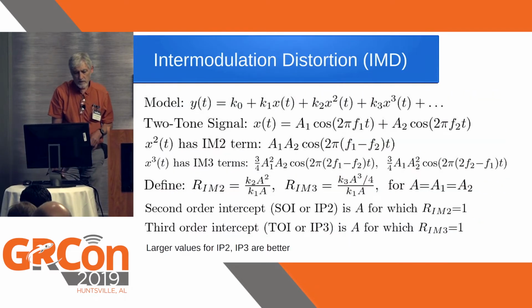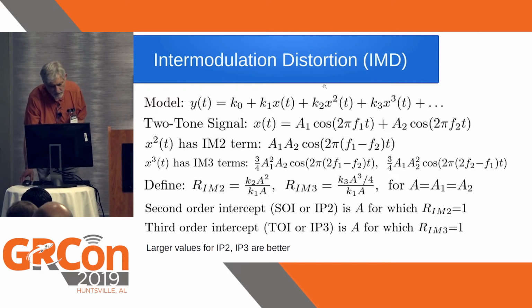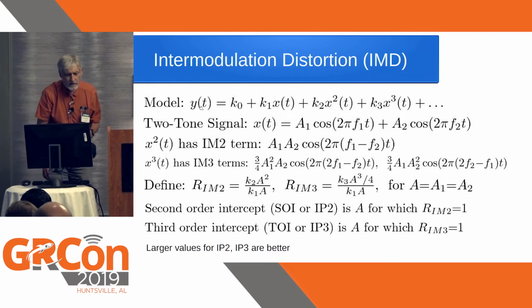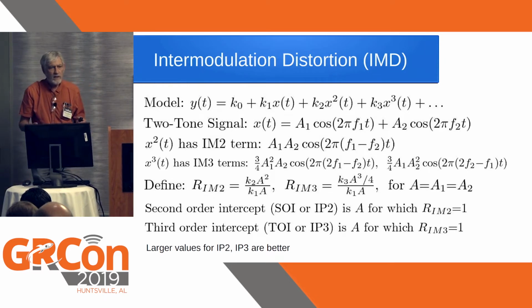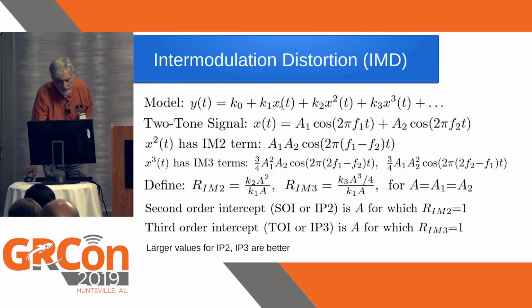Okay, so now this looks intimidating. That's an attempt to talk about the intermodulation products. And the main takeaway here is that when you go into the nonlinear region, the way you model this is in the form of a Taylor series of your signal. So x of t here, that's your signal that you want to model. And then you also get some x squared of t and some x cubed of t because of the nonlinearity. You also get a DC component here, which is less important. And each of those appear with certain factors.